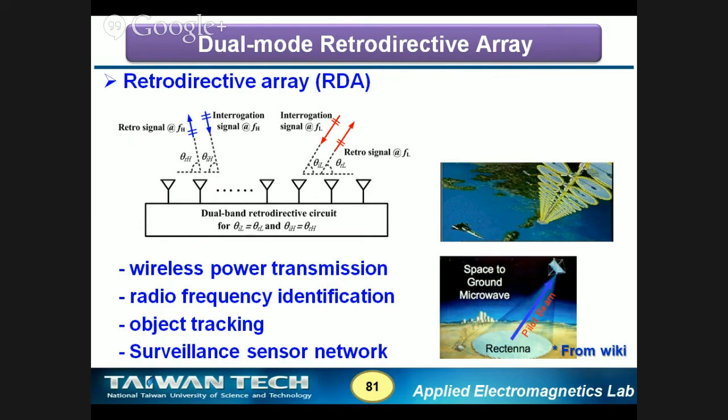We need a pilot signal to instantaneously echo back to the beam's direction of arrival. This is the application of a retrodirective array. Once you have illuminated the rectenna, we can use a very small, very tiny retrodirective array, and it can automatically generate the pilot signal, and the pilot signal can be retransmitted back to your satellite.